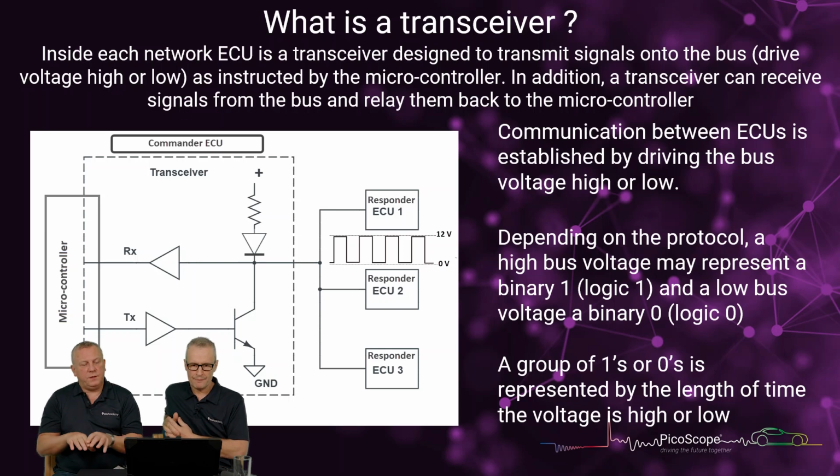Yeah. This is a bit like when you test the output going to any kind of load on a vehicle. If this was going to a bulb, before the circuit was completed, both sides of that bulb you would have the supply voltage. It's only when you provide a ground path, which is the job of the microcontroller, that the voltage will be used up in the load, and then you'll get your 0 or low voltage reference.